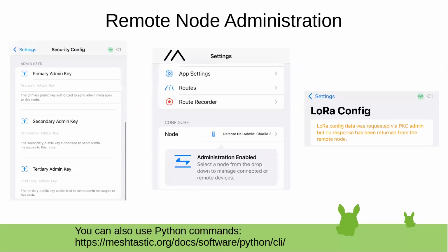And I've put a little effort into being able to do that via Android as well. I actually updated my green node there before I left the house today. I literally just downloaded the file onto my phone, unzipped it, plugged in a double-ended USB cable, and put it into DFU mode. It pops up as a little storage device, and I literally hit copy into there, and then it reboots and comes up on the new firmware. Literally, I can do that from my phone.